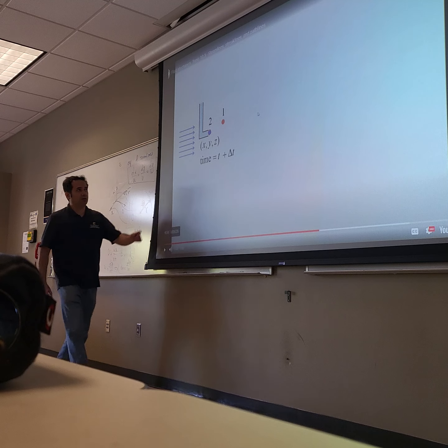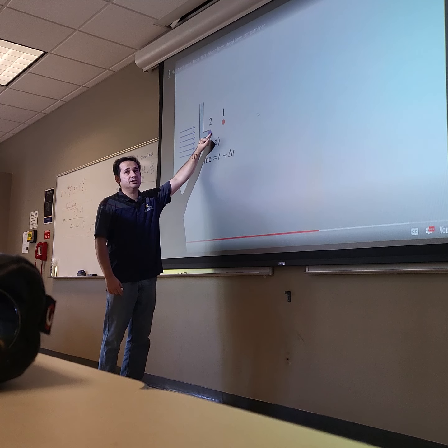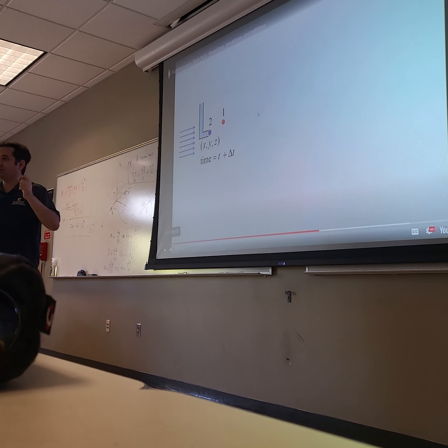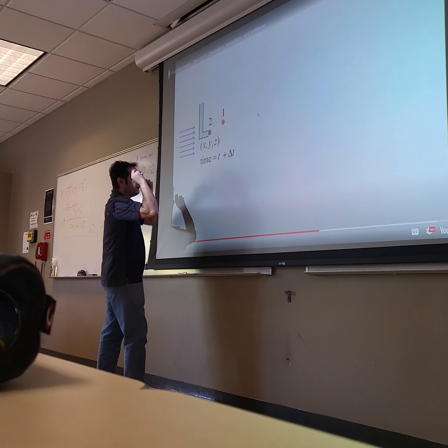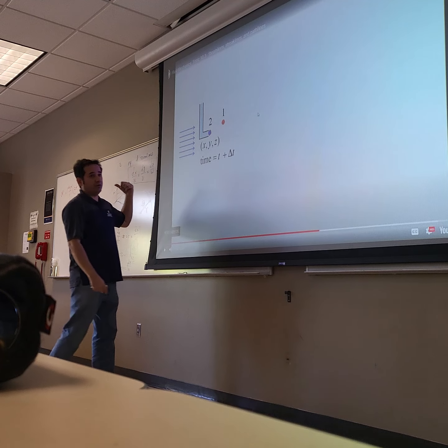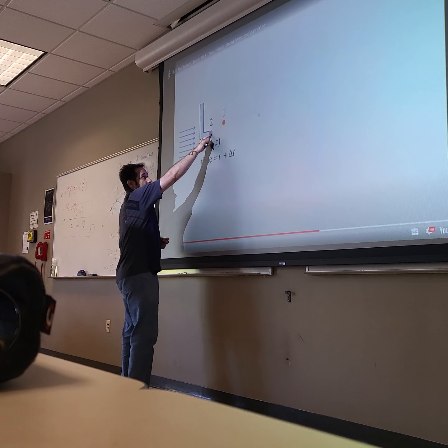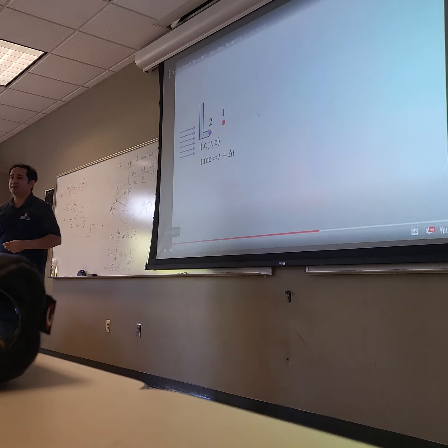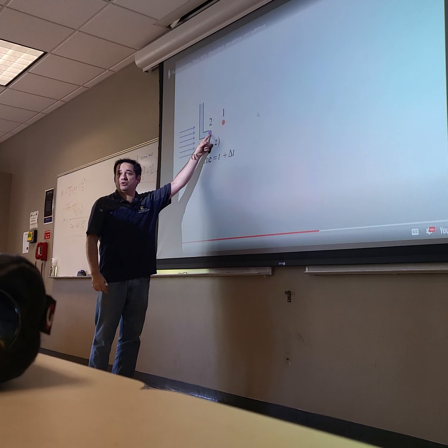Look at this location. If you consider this location, the fluid particles are going through it, not one particle, not two particles, a million, gazillion particles going through this point over time. Now, unlike the last problem, where I focused on the entire thing, if I focus on just one point and consider the particles that pass through that point, we call that streak lines. So streak lines are the particles that are passing through just one single point over time.